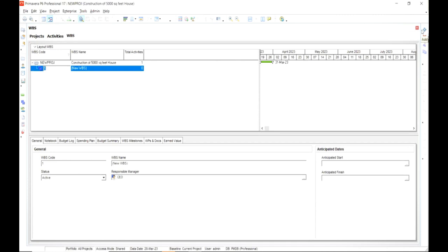For the WBS you can give it a code and you can also give it a name. I'm not going to change that code, and I'm going to name it civil activity. Now all the civil related activities will be part of this WBS. And then the second one is planning. Now by default, Primavera P6 made the planning part of the civil. So I want to change it.